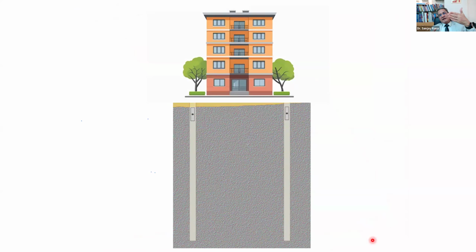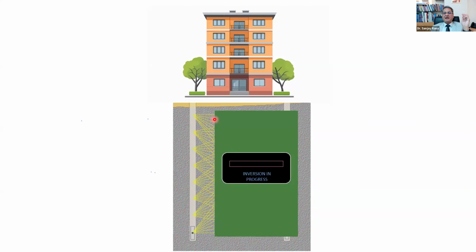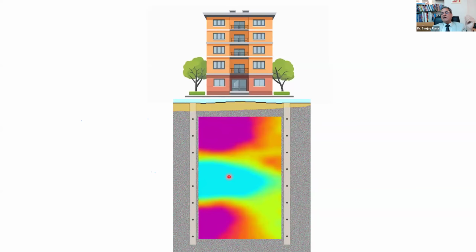But there is a road in the front and a road in the rear, which can be a service lane, etc. If you are able to put 2 drill holes on these roads on either side of your building and do your seismic tomography between them, once you process the entire thing, now you have all the information right under your building where your tunnel alignment is passing through. So this is a solution especially for people working on metro tunnels.